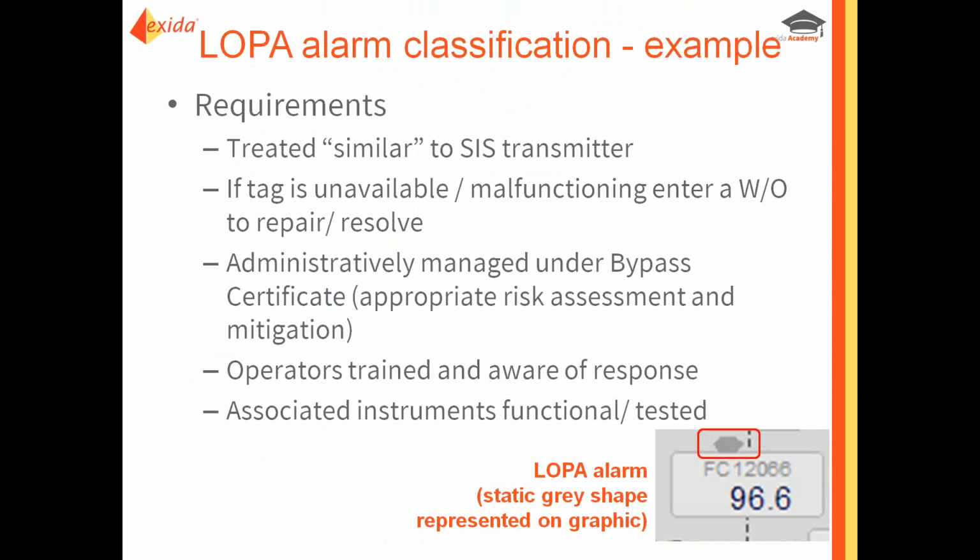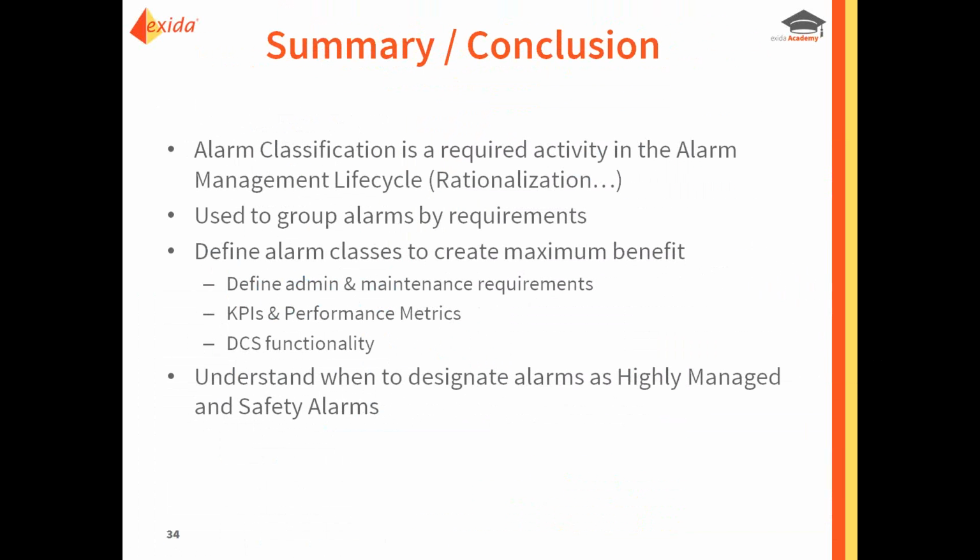You can see that written here. But what I really wanted to call your attention to was the fact that they wanted these alarms to also be presented differently within the HMI to the operator. So a different graphical symbol. So another area where classification can show up, and that the operator would be able to differentiate those alarms that are part of that class versus general process alarms.